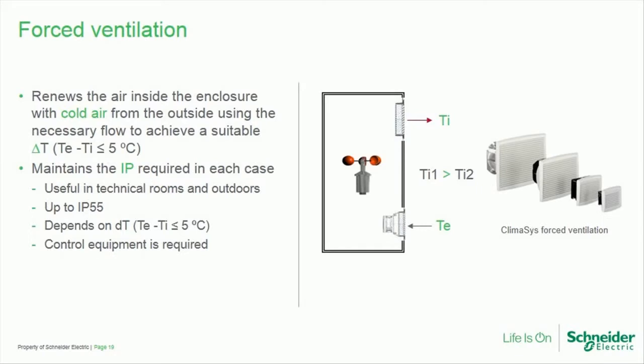Forced ventilation. The use of forced ventilation has many advantages. The value for money is very good. It helps to pressurize the enclosure because the output runs towards the inside of the enclosure. It should normally be installed at the bottom of the enclosure. At the top there will be an outlet grill to facilitate the release of hot air. An IP55 kit should be installed for IP55 values.